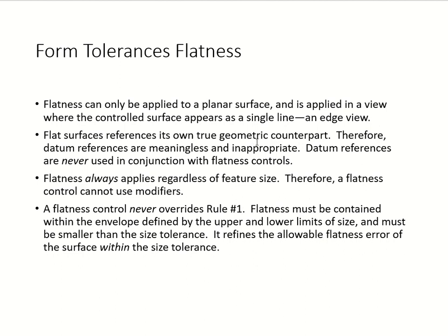reference their own true geometric counterpart, so we don't have to deal with datum references. That's what it's saying. In your control frame there is no datum attached to it, so we don't use datum references in conjunction with your flatness control. Flatness always applies regardless of feature size, again your RFS. So you don't have to use a modifier, MMC or LMC, because it always applies regardless of feature size.